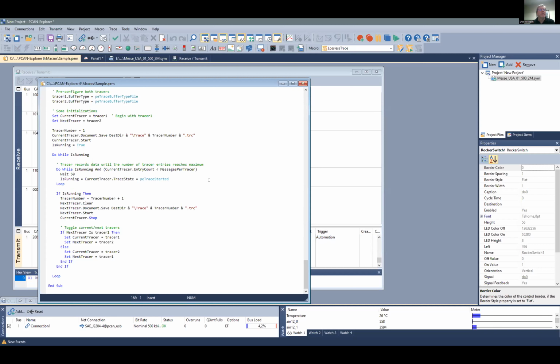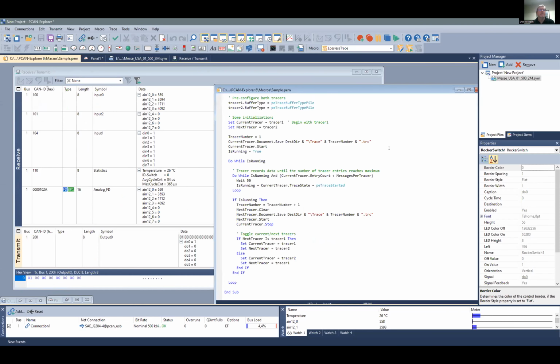So in the background, the PCAN Explorer receives CAN frames, decodes them, and creates signals. The signals are like a variable that I could use inside the script. So I can ask, is digital in set, yes or no, or what is the value, and then I can do something. That's possible. And also outputs. I can calculate something and set it. I want to set the analog output to 450, and then the system creates the ID and sends it out. That's possible.